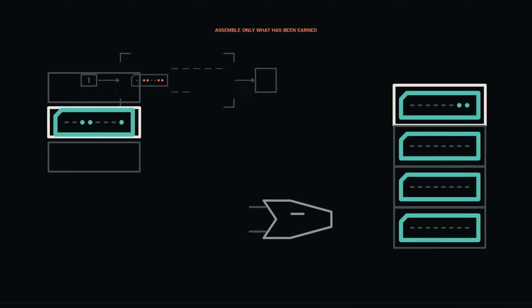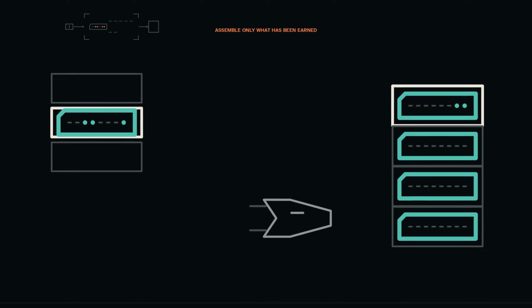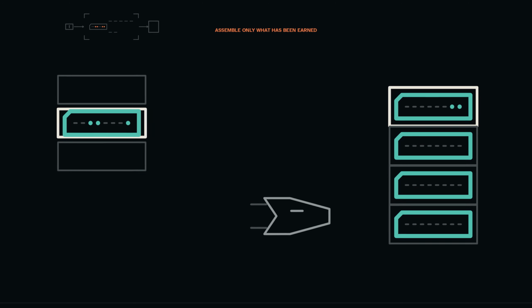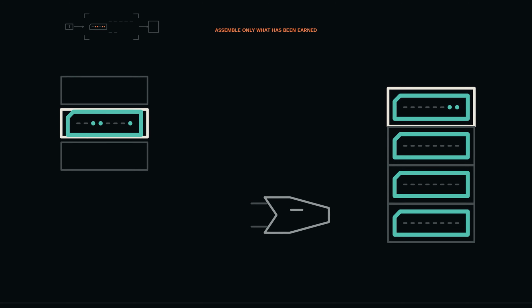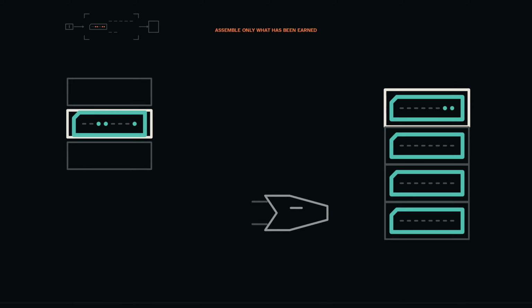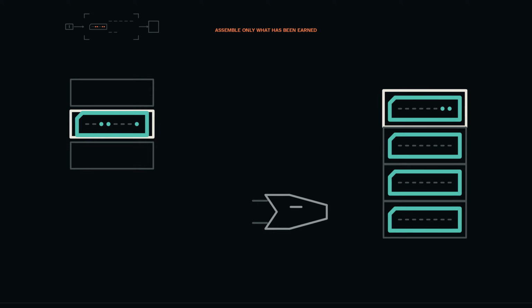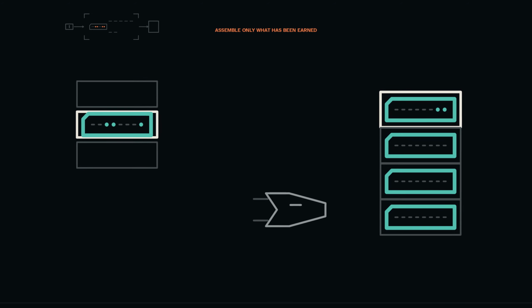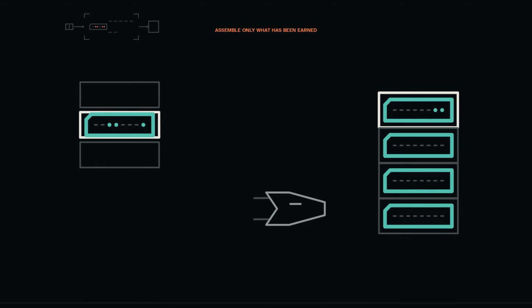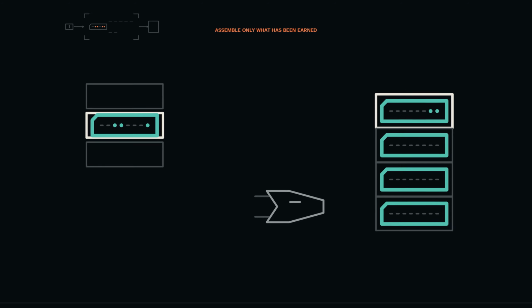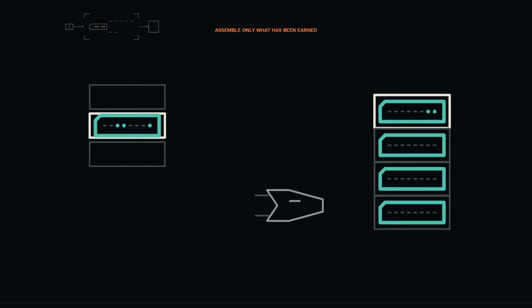A module earns its place here by making a precise promise at its boundary. A register can hold one 8-bit value and replace it on a declared edge. The arithmetic and logic unit can apply a selected operation to its inputs and expose a result with flags. Memory can return the byte at one selected address, or replace exactly that byte. These promises are smaller than the physical circuitry inside each module, but they are not vague. We can reopen any one of them when a question depends on its interior.